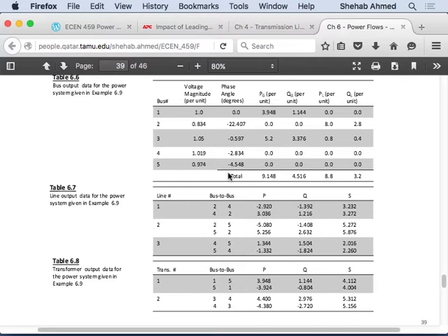But if you connect an electrical load to it, you're doing what? Then you have current flowing in a conductor in a time-varying magnetic field, which creates a force on that conductor, right? This force opposes the force that created the motion. It opposes the torque that was placed on that generator, right?